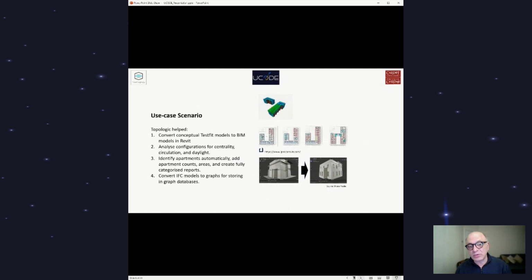What he does with that is he takes a cell, which is a Topologic cell, and slices it with planes, with surfaces, Topologic faces. And with one click of a button, it converts it into a fully ISO standard IFC file. All the windows are there, all the details are in there, the doors, even the cornices, and it even has an embedded energy model inside of the IFC file. And that can be developed further using another software called Blender BIM, which runs within Blender for native IFC manipulation and editing. So really, really powerful.